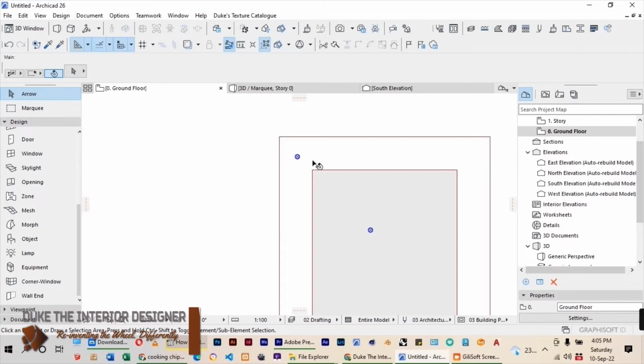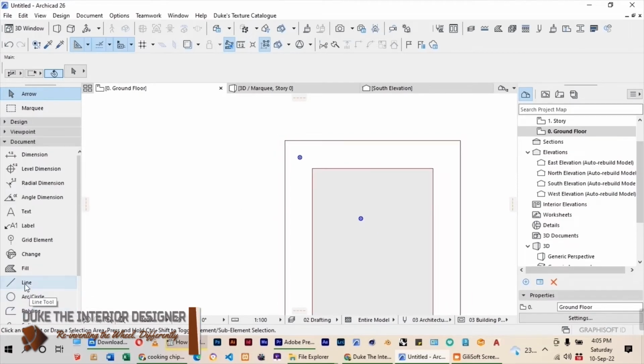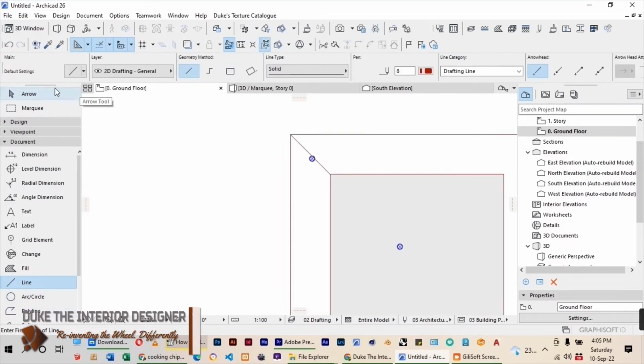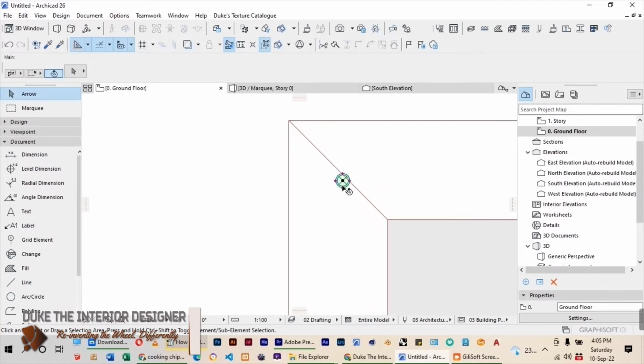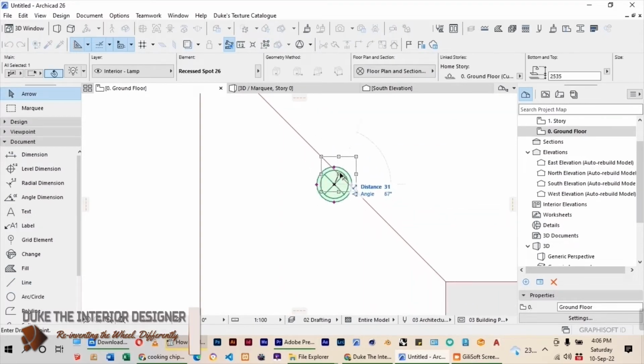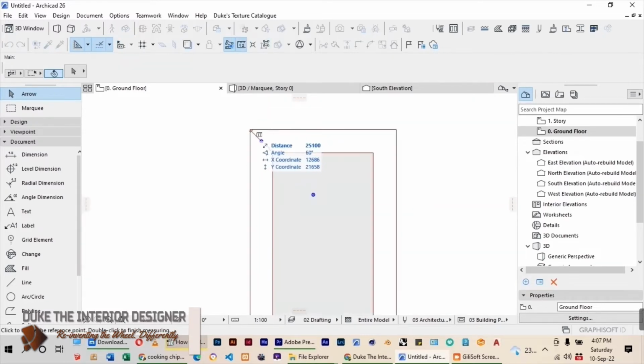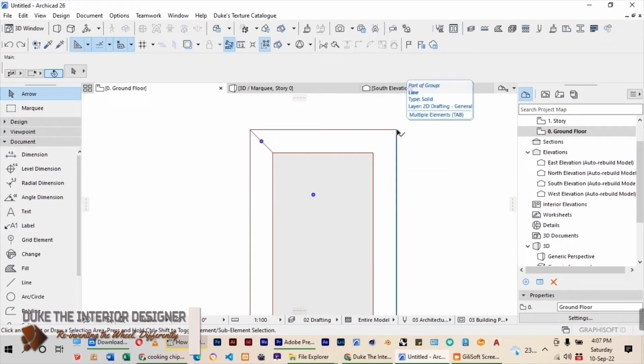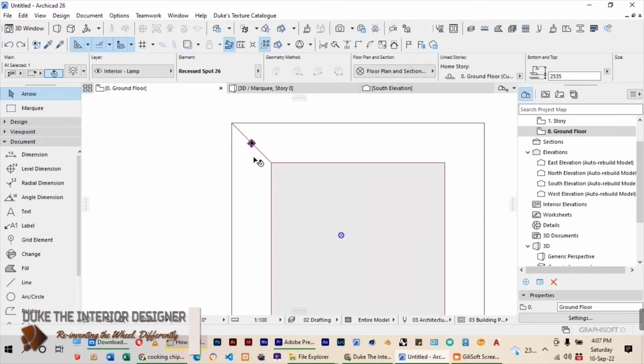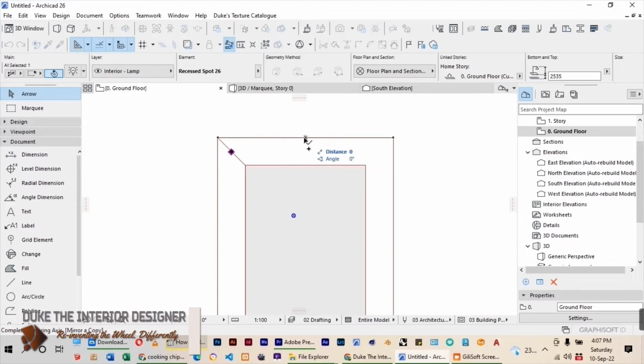I have to make sure that this is in the mid. Normally what I do is look for the diagonal and then press this in the mid of that diagonal, which is here. For the lights, I'll check on the measurements. I have 4.4 meters. That means if I do 3 lights, I'll have a difference of about 2 meters on either side, which is quite efficient for illumination.